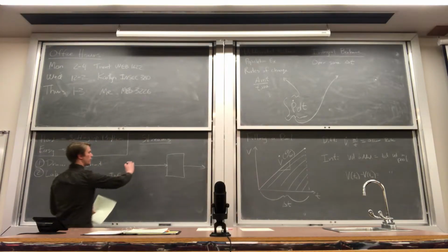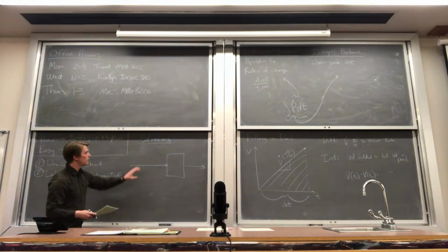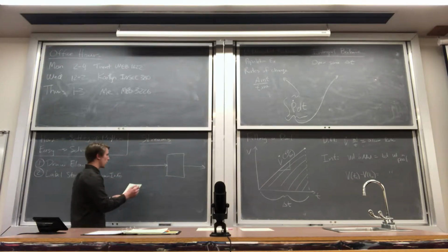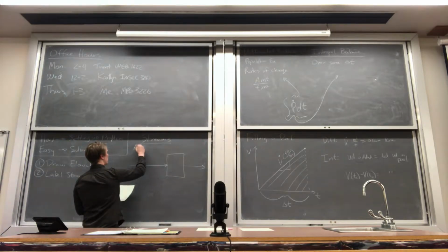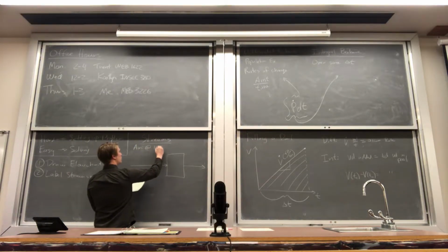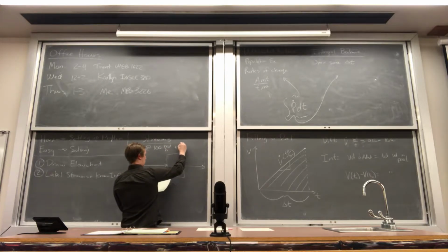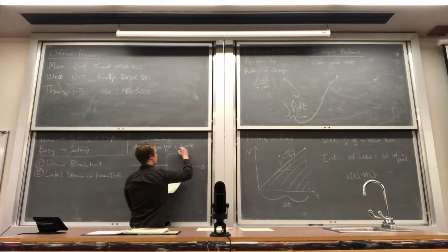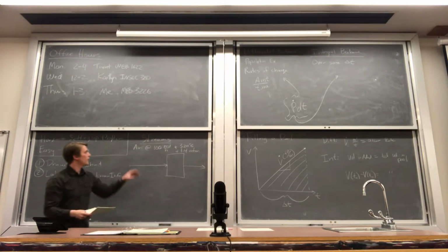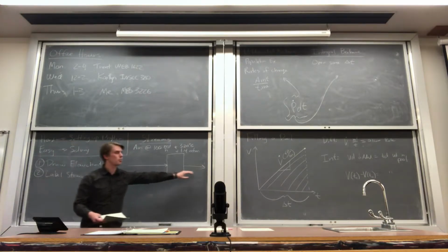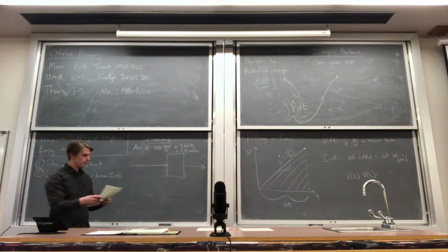So when we talk about a flow stream, what we need to know is basically all of the properties associated with it. Temperature, pressure, composition, and total flow rate. And so for example, if we said we had air at 100 moles per hour, 320 degrees C, and 1.4 atmospheres. We have to communicate this information and draw it out on our process flow chart because the temperature and pressure that it leaves at may be slightly different.